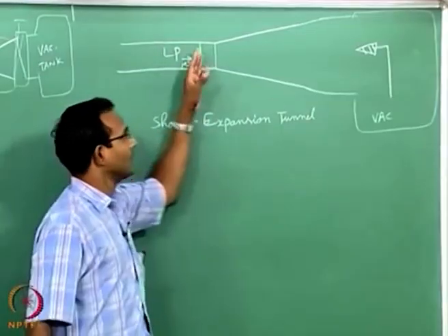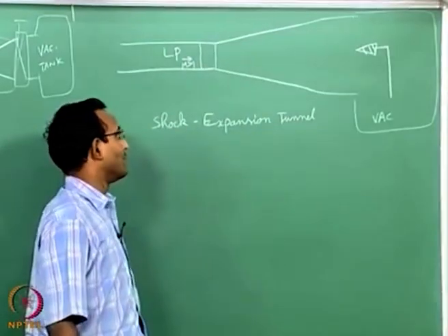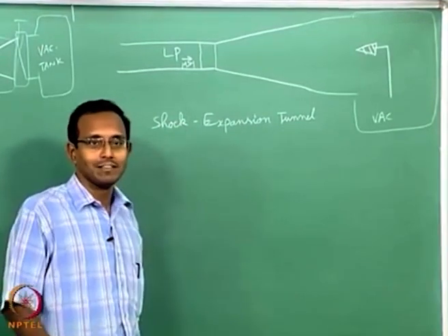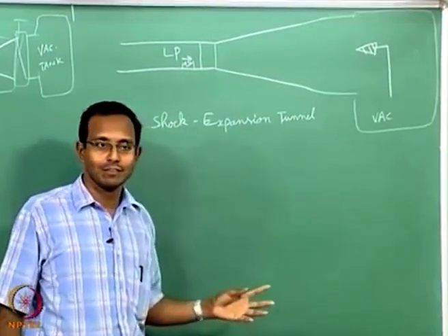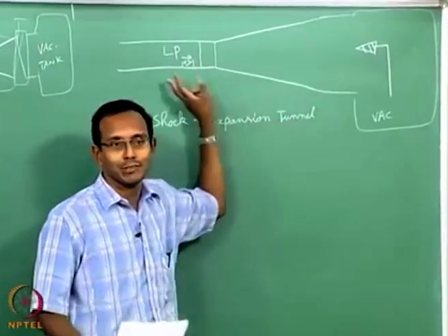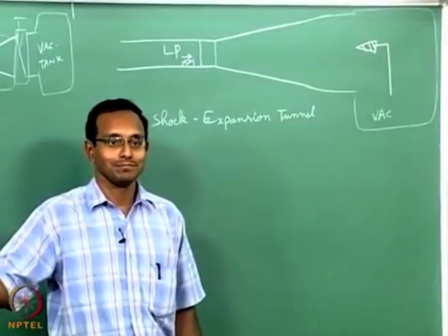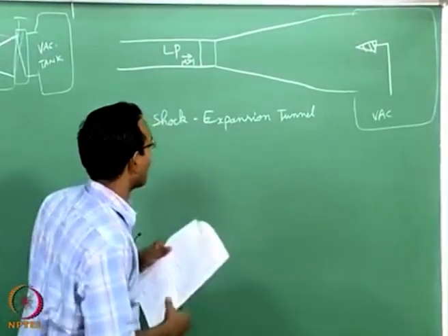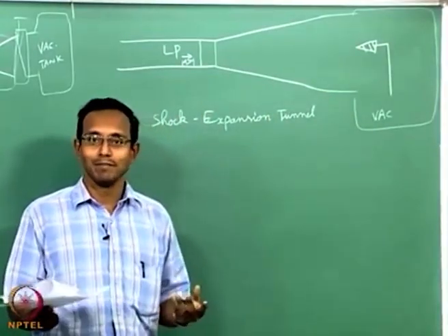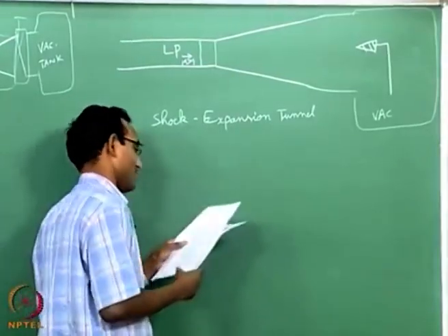Okay, basically it is a shock tube and now the flow behind the shock is expanded further to get to whatever Mach number you want. Typically they use this kind of facilities for really high Mach numbers, something like hypersonic flows. We have a hypersonic flow facility where we can go all the way up to Mach 25. Of course it just depends on what area ratio I use. Beyond some point I will not believe the data because it may become non-continuum. I can make a nozzle for Mach 100 also, but at that point the pressures are so low that it may become non-continuum. Then I have to worry about, is my data really valid? Okay. We will not worry about that right now.